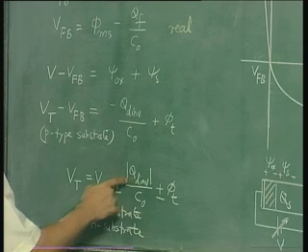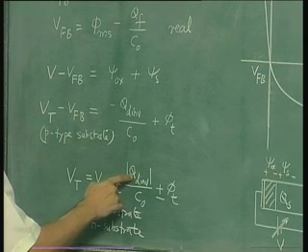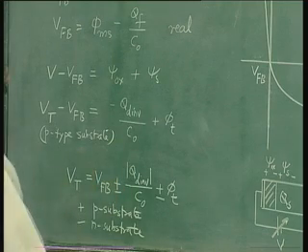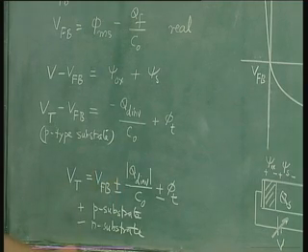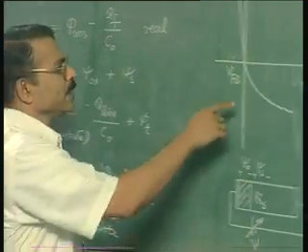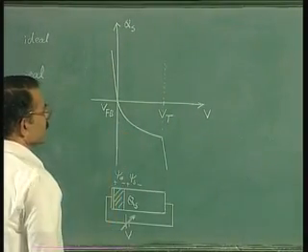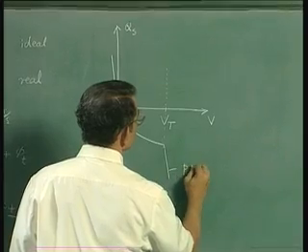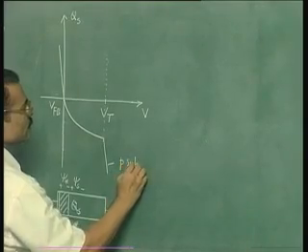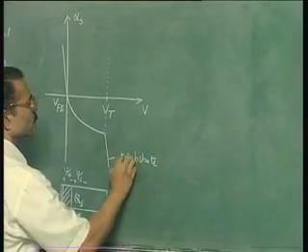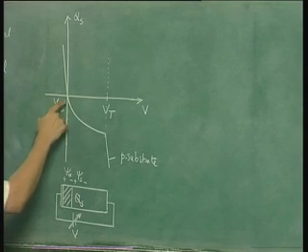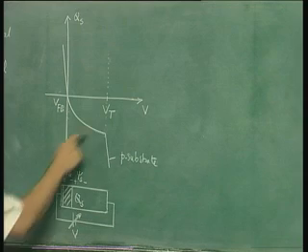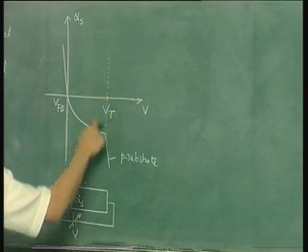So notice that this is modulus of the depletion charge at inversion, for which we have written an equation already in terms of the doping. Now coming to the QV relation, this is the QV relation for p-type substrate, where the charge is 0 for voltage equal to VFB, and beyond threshold you have inversion.